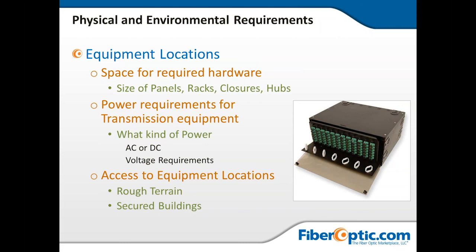You want to look at the size. You want to look at if you're going to use racks or wall mount. Power requirements for your transmission equipment. What kind of power am I going to use? Am I going to use AC or am I going to use DC? What are my voltage requirements? What are my backup requirements?